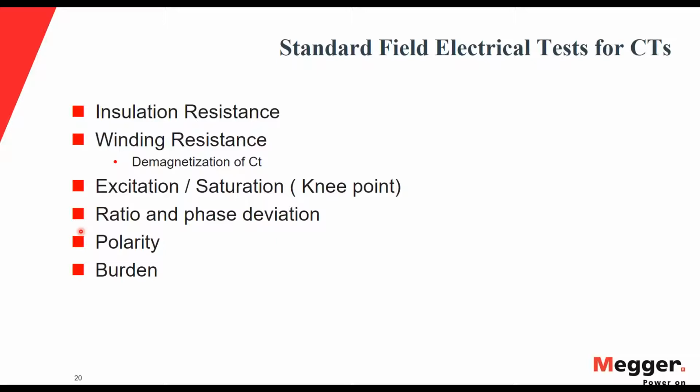energy. And then last but not least is the burden test. This test is not defined for the CT itself, but for the burden connected to it. You need to measure the burden of that device, and not only the device itself, but also the leads.